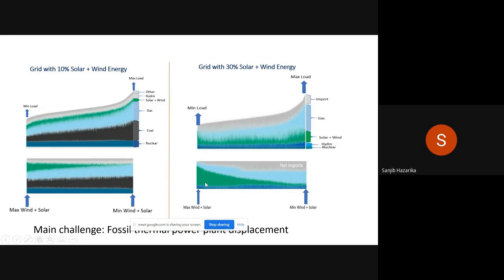So what happened here, you can see at a certain point the electricity production from solar and wind is quite significantly high, and it reduces after some time. So the gas-based power plants try to make up whatever reduction happens in renewables, and they also have to import a certain percentage of their electricity demand to meet it. So that basically shows how the grid system works.